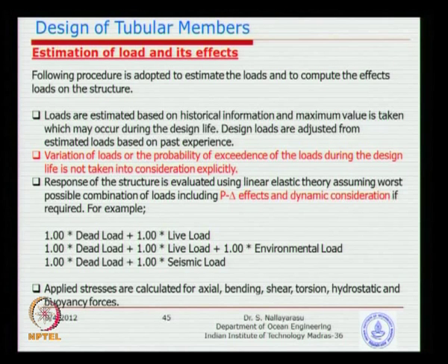The coexistence, or so-called probability of coexistence, has not been investigated. If it is investigated, you may actually see that during a high storm nobody is going to have, for example, high live load, so you can actually reduce it. That is not done in this allowable stress method, because we are not actually evaluating that side of the load effects. So, that is one of the disadvantages that we see in using the allowable stress method.